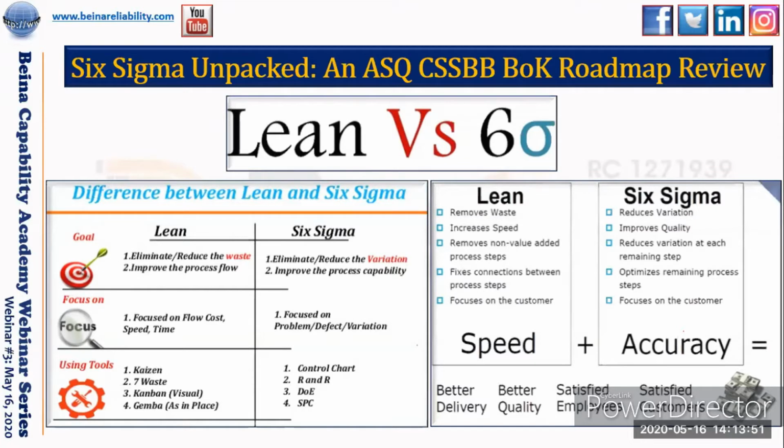You'll be looking at gauge R&R, which is repeatability and reproducibility, where you are able to say that if different people are testing, if different people are using different tools to test, how can we ensure that there is minimum variation in the result both of them are generating? And of course, the big part of Six Sigma would be statistical process control, which is explained better in other slides.